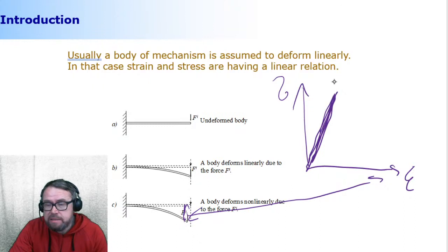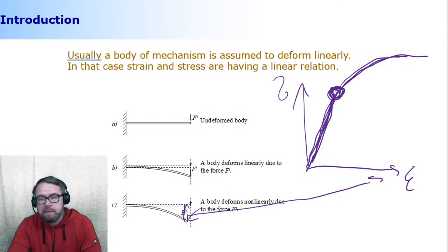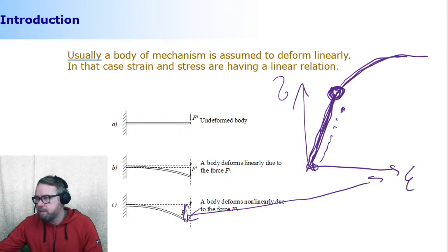and then there's a certain point beyond which, if you take strains more than that, there is a plastic deformation. Usually that's when the curve is no longer linear but non-linear. If you travel here, go to this point, and check your load path, you go exactly where you started. So it's linear deformation.